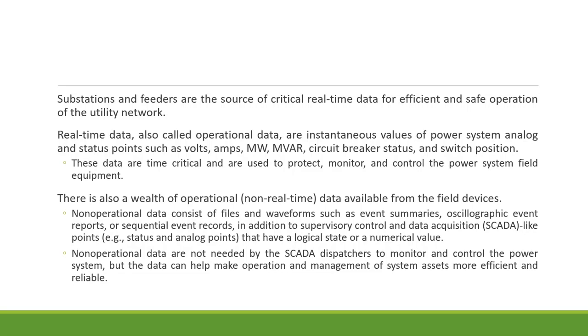There is also a wealth of operational data available from the field devices that is non-real time. Okay, so we can call it non-operational data. This data may include files and waveforms such as event summaries. Certain event happened, so exactly what was the reason, what was the voltage and current at that time, and what actions have been taken. So you will get these as non-operational data. It could be your event summaries,